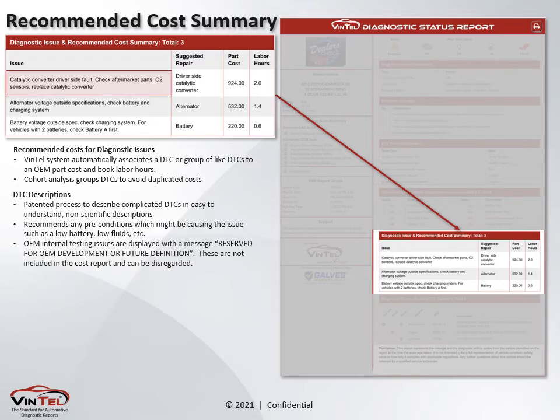One of the challenges faced with anyone looking at a DTC report from the OEM description is the vagueness and the duplication of the DTCs. For instance, many times an oxygen sensor may have 5 or 6 different DTCs, but it's still all the same oxygen sensor that's bad. Many people, if you're not trying to repair it, or even if you are, just know you replace the component. You don't need to know why it failed or when it fails. And that's really what you're seeing here.